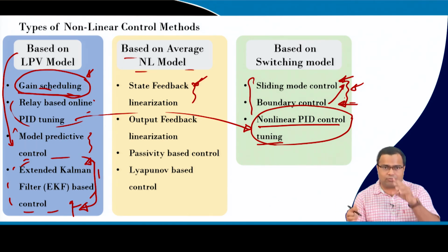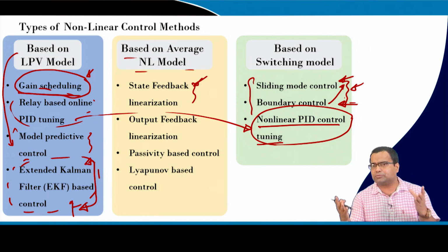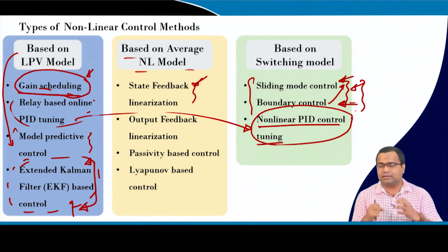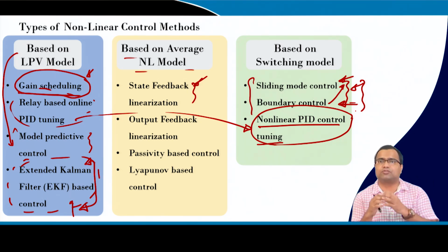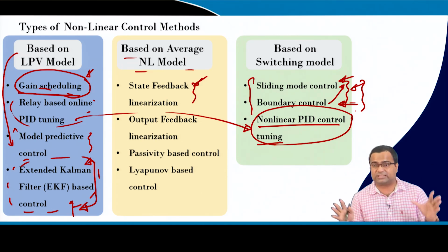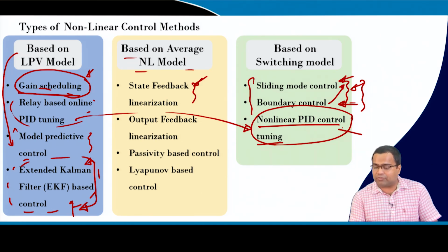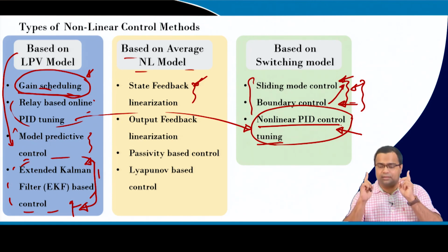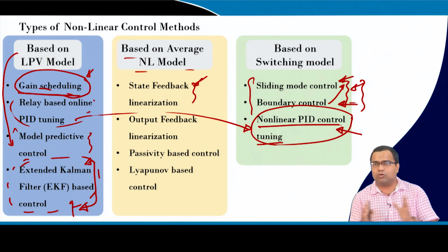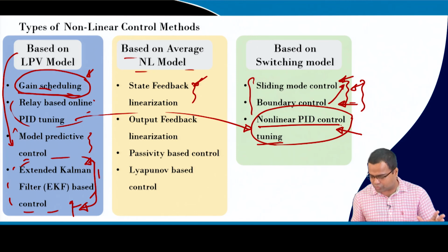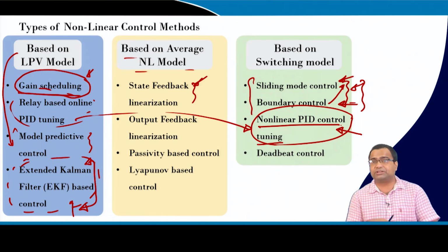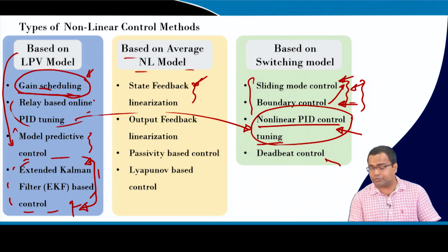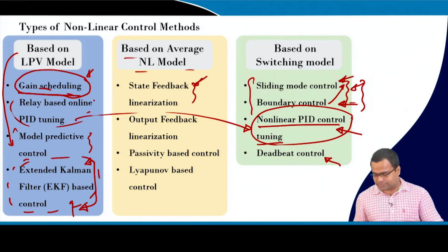So, it can require more resources, and most of the time we interface this kind of control with a PWM control under steady state. So, they combine nonlinear and linear control to achieve the desired response. But here what we are going to talk about is a single PWM control that can achieve the whole performance. You do not need a separate controller, and you can also use deadbeat control, like a time optimal control, to achieve the fastest response.